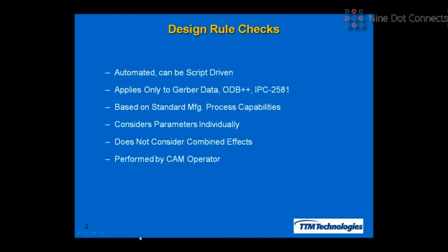So let's look at some of the different things that come into play on the top level on DFM waivers and deviations. And keep in mind that well over 2/3 of what I see come in, as far as new designs, there is some sort of waiver or deviation request right up front. So what I've done is I sorted these out into the electronic data side of things, and then also into the manufacturing side of things on the second set. So I guess the first thing would be an incomplete fab package, and we'll go into more detail in a few slides exactly what that is.